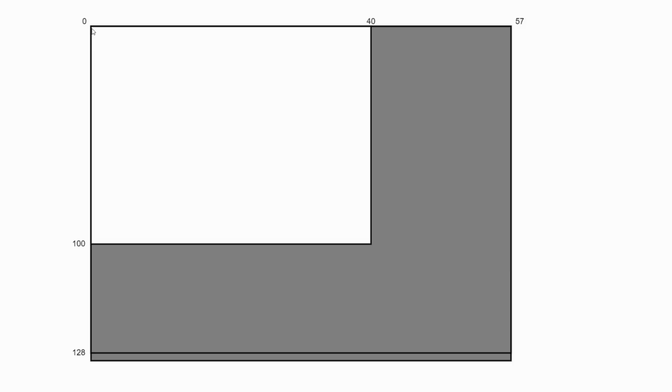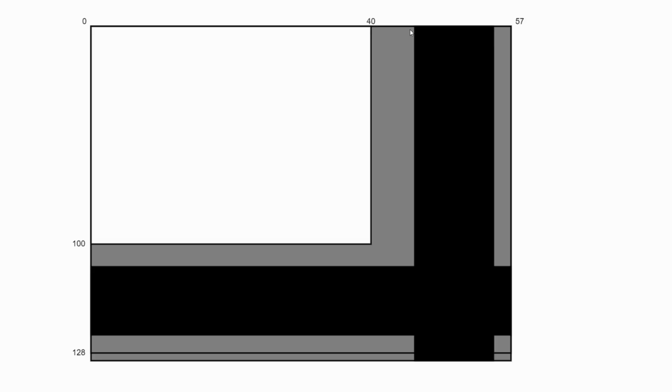It starts its run at the top left of the active portion. It displays characters. There'll be 40 characters or 80 bytes, which is 320 pixels, and then it starts the right-hand border of the screen. And this is done in the background color, whatever that currently is. And this is where the electron beam gets sent back to the left-hand side of the screen by a horizontal sync pulse.